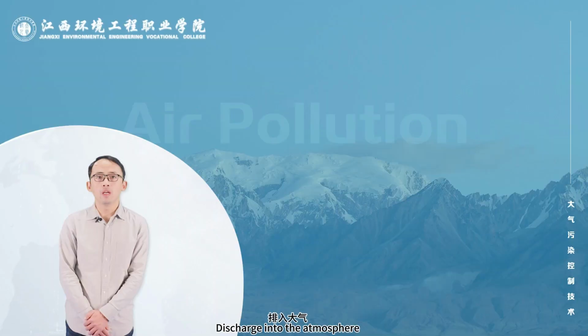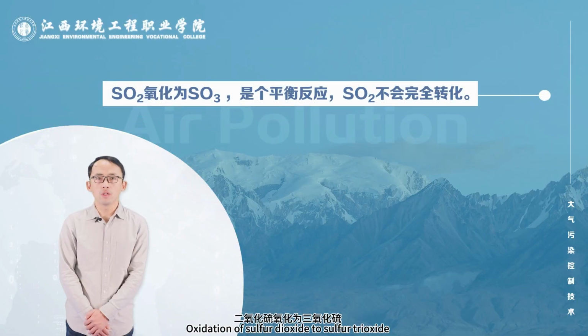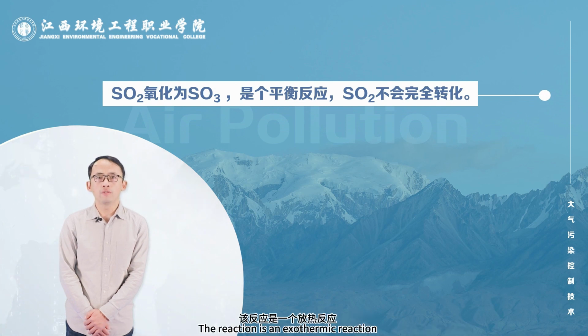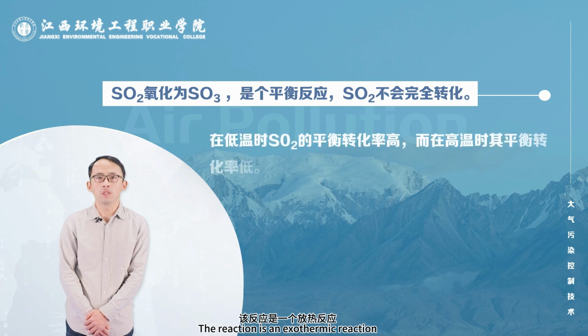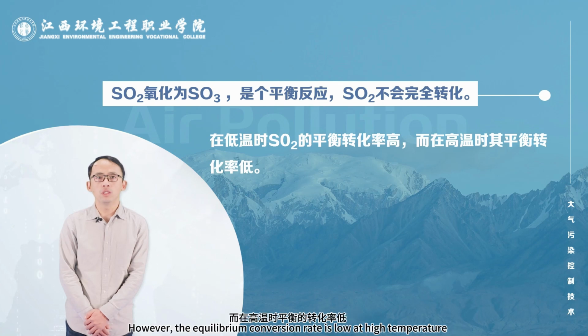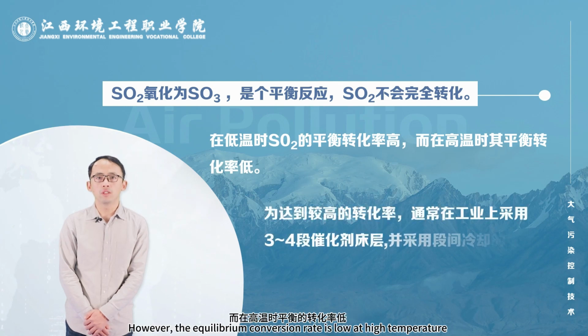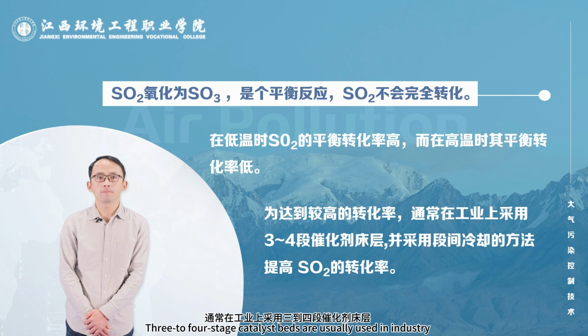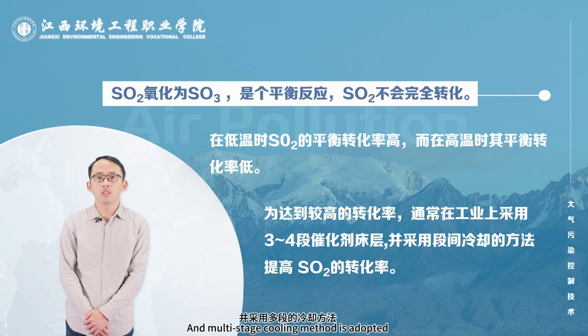discharged into the atmosphere. Oxidation of sulfur dioxide to sulfur trioxide is an equilibrium reaction, and sulfur dioxide will not be completely converted. The reaction is exothermic. The equilibrium conversion rate of sulfur dioxide is high at low temperature, but low at high temperature. Therefore, in order to achieve a higher conversion rate, 3 to 4 stage catalyst beds are usually used in industry, and a multi-stage cooling method is adopted to improve the conversion rate of sulfur dioxide.